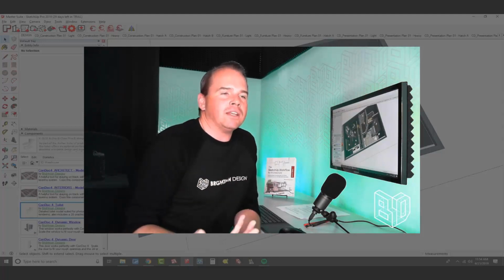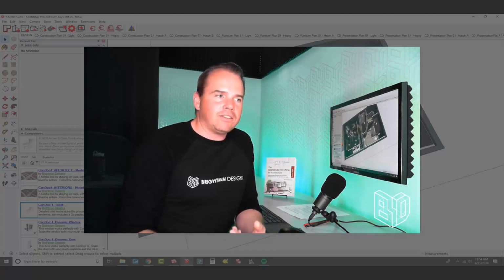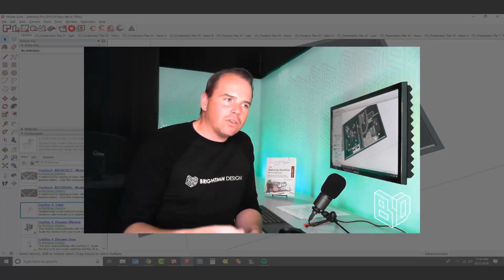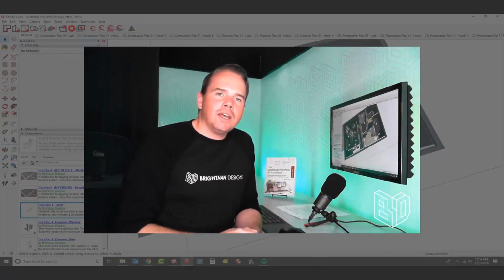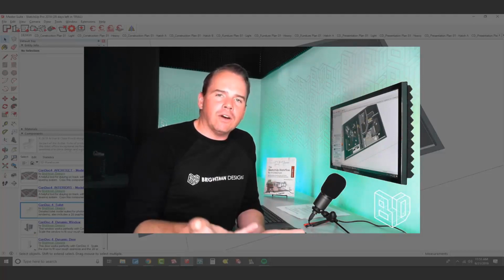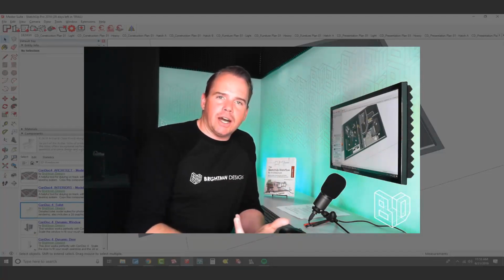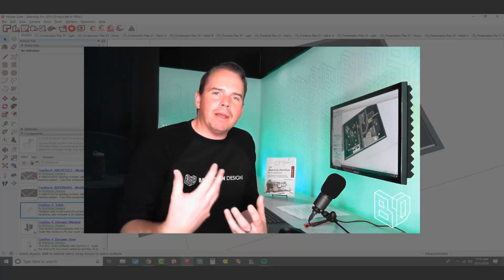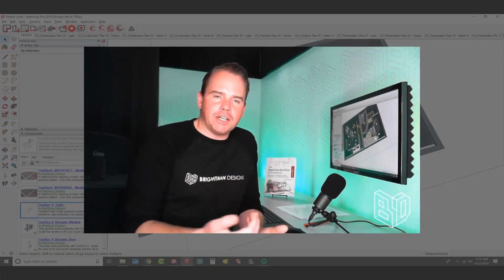And I can see why you'd think that, because when you're in SketchUp, there are no line weights. It's not that traditional CAD feeling where you have a line thickness or pen settings that correspond to colors. There is no indication really of line weights in SketchUp. We do have profiles and section cuts and depth cue, but those seem to be buried and many people don't find them, so they just think there's one line weight in SketchUp.